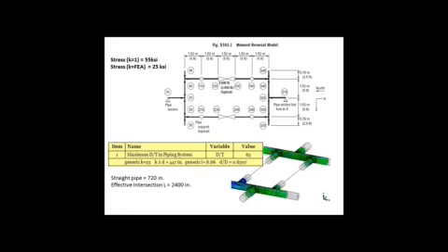This is the typical example of a tight piping system. Here what you see is no elbows, very little straight lengths of pipe, high D over T ratios, KD of 447 for a single T. There's 6 T's in this model. The T effective lengths are more than 3 times the straight lengths in this pipe. When we ran this with FEA tools, the stress range went from 55 KSI to 25 KSI.